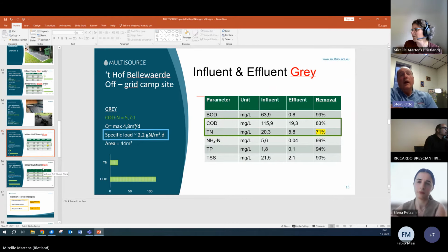But what I can't see from looking at your table there is the difference between TN and ammonia. Is there organic N that still has to get to ammonia, or is it nitrate that's already gone through that stage? So that would be a question to ask, maybe take a measurement. I mean, that's maybe a difference.